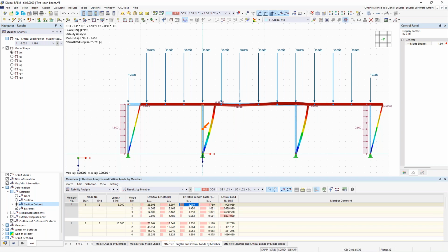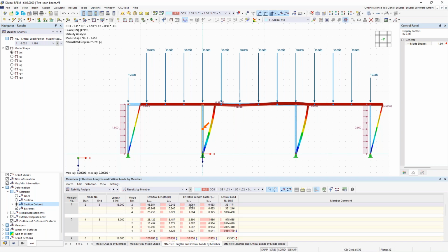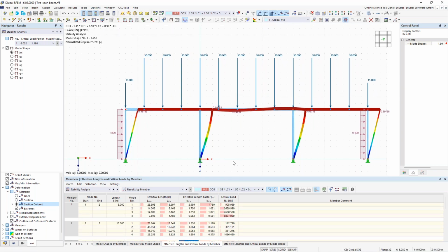Okay, here we have this value, remember it, almost 3, and here also almost 3. So what we do here is that we consider this for the stability analysis for my steel design. So we have 3 different methods for the stability analysis for my steel structures. Now I refer to my method B, so to the last one. And as you can remember, there we don't need to consider any second order effects, but we need to consider the right buckling lengths. Okay, how can we do that?